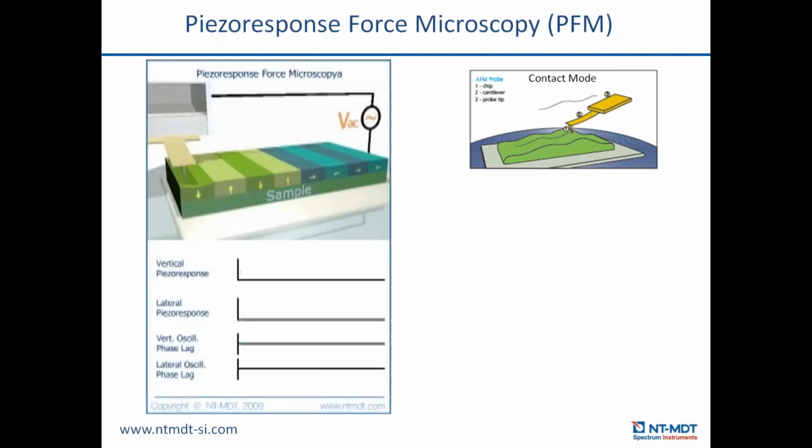So the next section of my lecture is about a pretty big class of smart materials. By definition, all the piezoelectric materials can be defined as smart materials. To study piezoelectric materials, we use piezoresponse force microscopy, and it classically works again in contact mode.